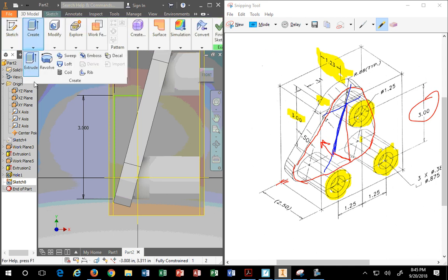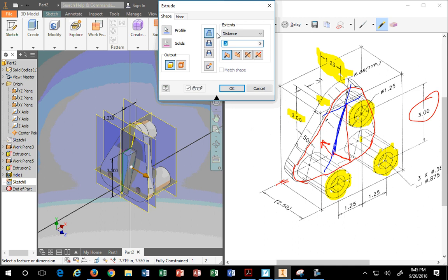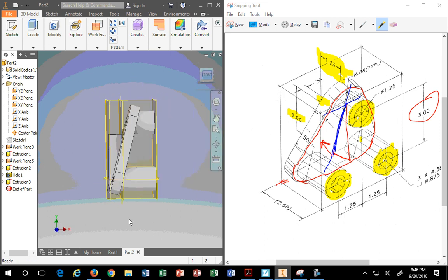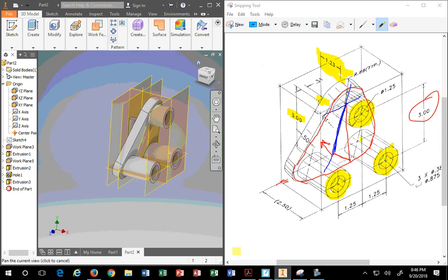Your last step will be to go ahead and do the extrude of this back fin mid-plane, a distance of 0.31. Mid-plane though, mid-plane, and hit OK. And there you go, that's your rib stuck on the back of it. My guess is there's something wrong, because why would it be there? It's not flush, it makes no sense. But those are the dimensions the customer gave us, so we have to go back to the customer and say, here's a drawing, based on your specifications, do you really want this? And make them verify it. And that ends how this would be built. That's how you would build this.